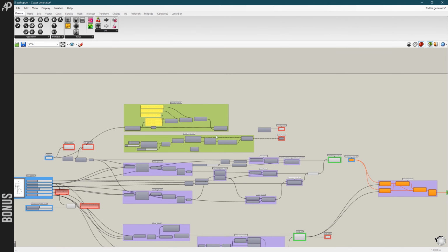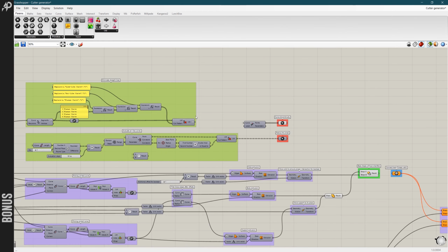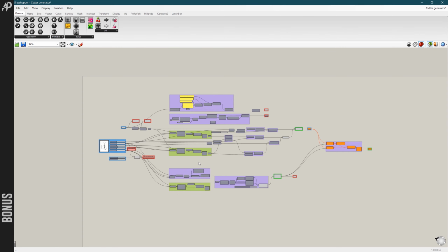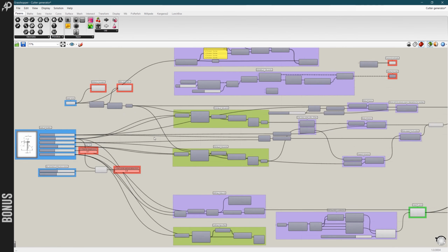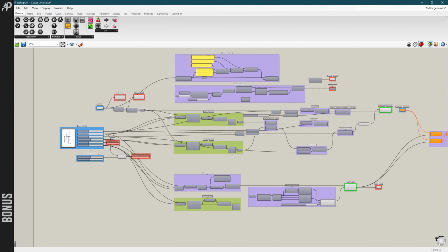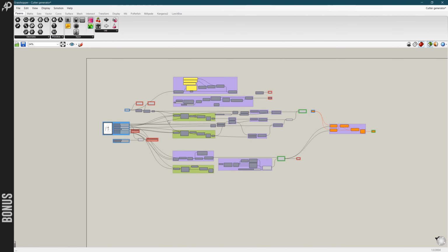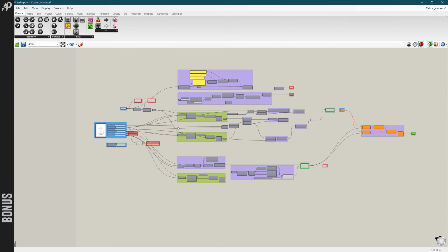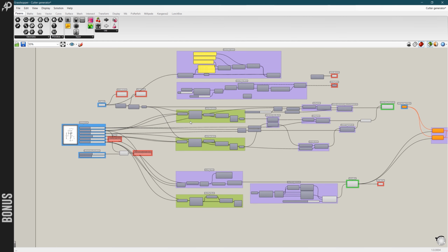This here, all this here, is just radius analysis. Wouldn't have to be here. This, and this wouldn't have to be here if Grasshopper was able to offset curves on the correct side every time. But sometimes it was offsetting using a positive value outward, and sometimes using the same value it was offsetting inward.